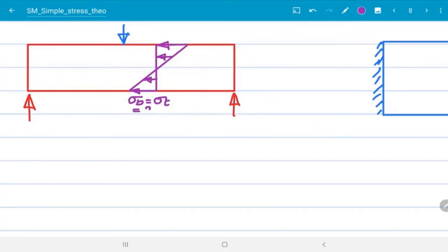200 megapascal. Right. The top surface at this point, right? At this point, sigma B is equal to sigma C, compressive stress, that you answered already. The value is minus 200 megapascal. Right. Now the interview question comes in. Which is critical?